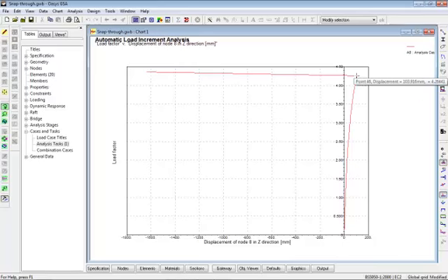If you can read that, it snaps through at a load factor of 4.26. So a factor of safety of 4.26 against snap-through for that particular loading, but obviously there might be other load cases to check, so this can be a very useful operation for these types of structures.